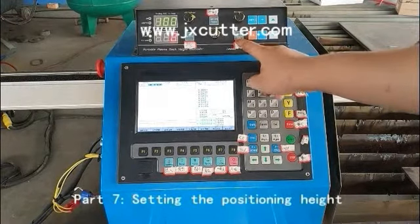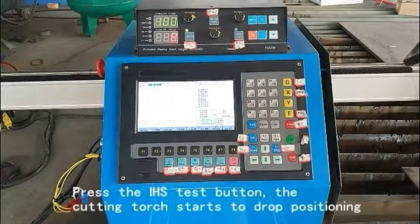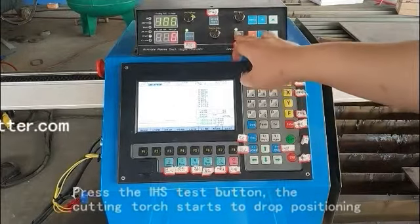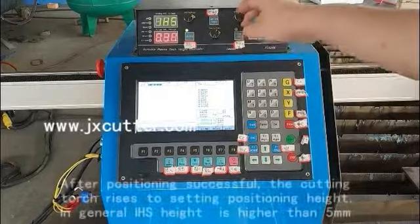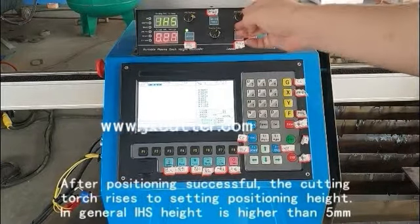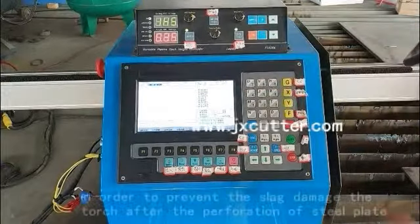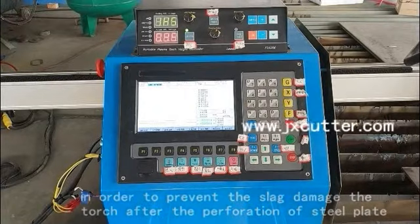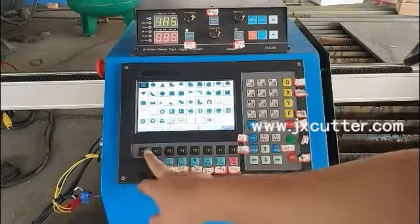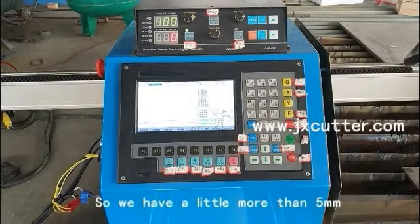Part 7, Setting the Positioning Height. Press the IHS test button, and the cutting torch starts the drop positioning. After positioning is successful, the cutting torch rises to the set height. The IHS height is generally higher than 5 mm, in order to prevent slag from damaging the torch after the perforation of the steel plate. So we have a little more than 5 mm.